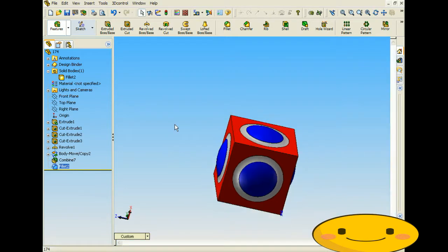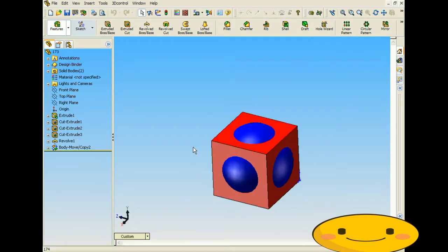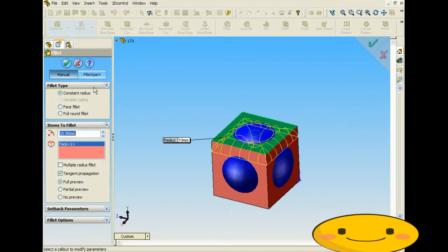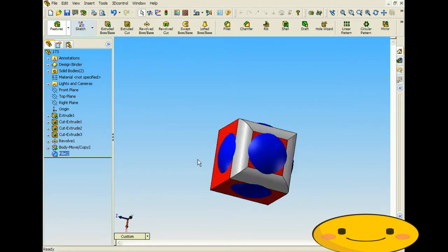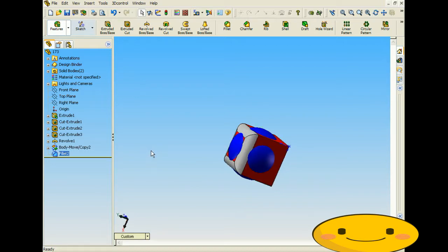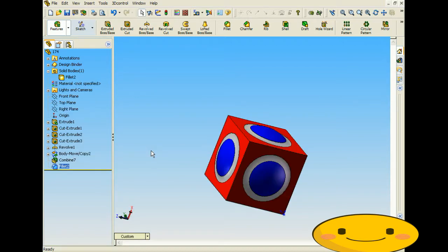And you can see that by what we get here, and when we add a fillet to here, what we get is totally different. It's not what we want. And this is just the relevance of why we're adding two together to make one body. And that concludes our tutorial on how to see the relevance of a Combine Add within SolidWorks.